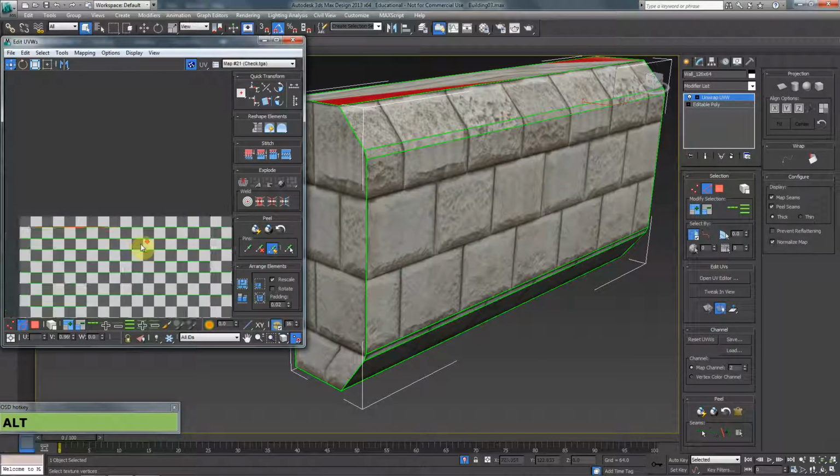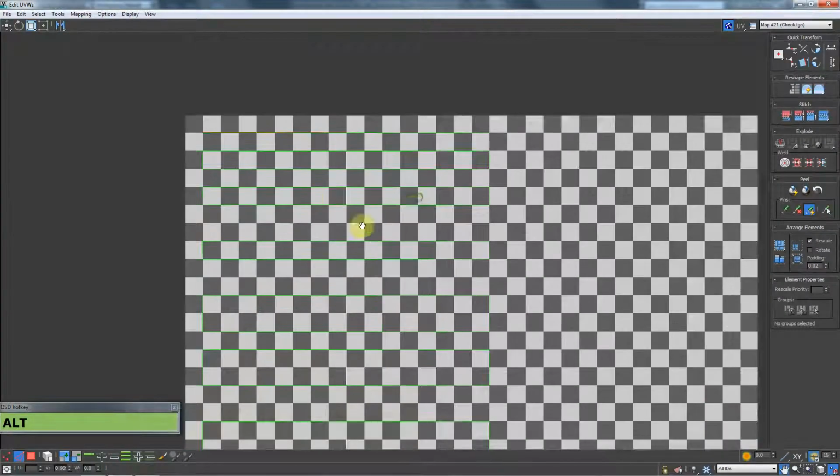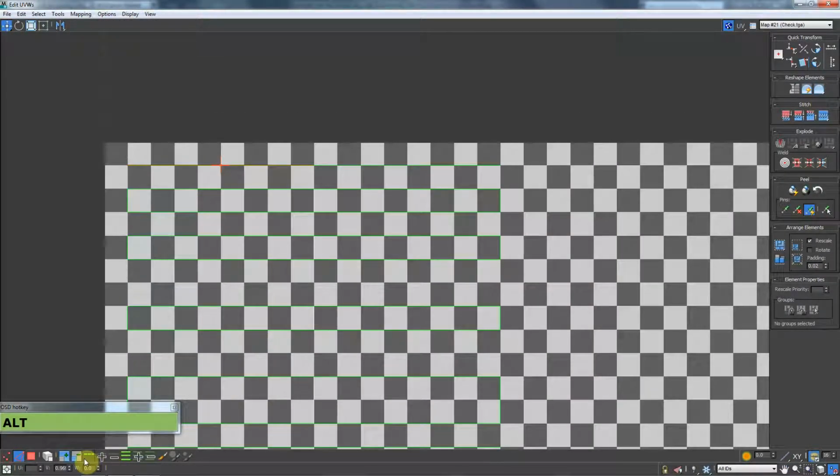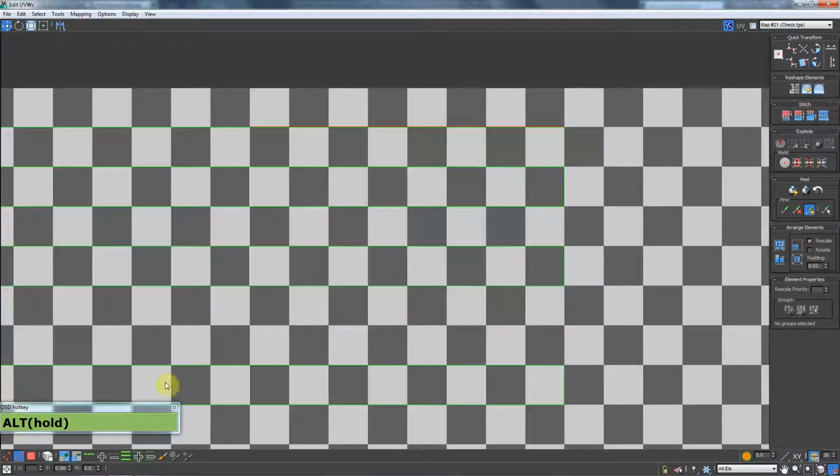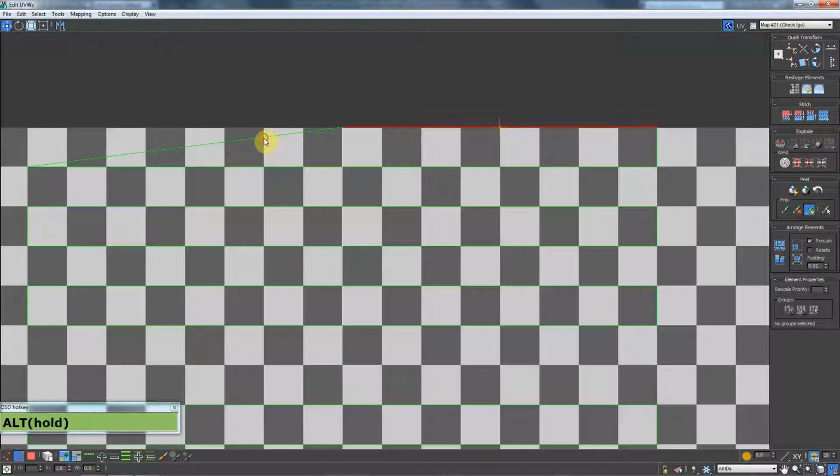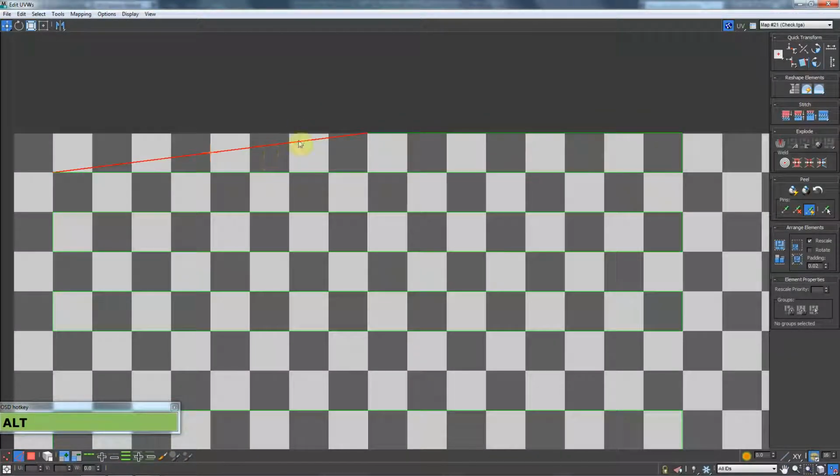It's difficult in this case, as you can see, to select both. I could loop it and try to move it, and it doesn't allow me, because they're right on top of each other, it doesn't allow me to move them both at the same time. So it only moves one. That's fine. When I move one, I can select the other edge. I can go to select and then convert edge to vertex.